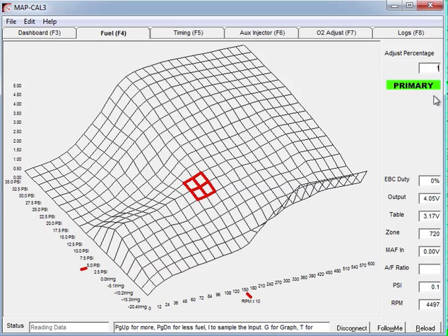If I change that to 1% and move the cursor and press plus, you'll notice the movement was significantly less than previously. Plus plus, minus, and as I press the plus key or the minus key, you'll notice in the status box down the bottom left of the screen a brief message. That message says writing the zone, so it's real-time tuning of that zone. So in graph mode you can only change one zone at a time.